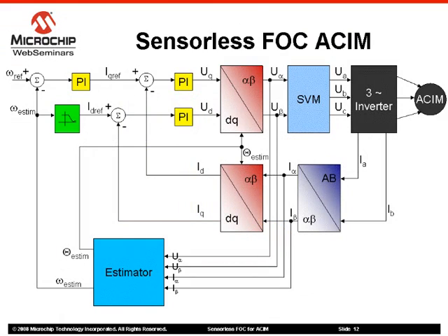The key to understanding how field-oriented control works is to form a mental picture of the coordinate reference transformation process. If you picture how an ACIM motor works, you might imagine the operation from the perspective of the stator. From this perspective, a sinusoidal input current is applied to the stator. This time-variant signal causes a rotating magnetic flux to be generated. The speed of the rotor is going to be a function of the rotating flux vector. From a stationary perspective, the stator currents and the rotating flux vector look like AC quantities.